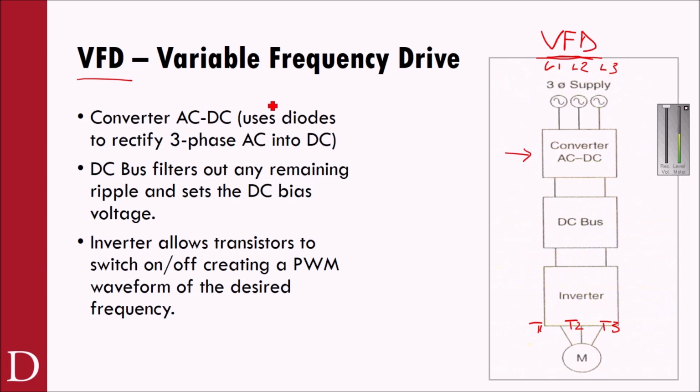Essentially in there's a bunch of diodes, and those diodes are used to rectify the AC voltage coming in into a DC voltage. You imagine diodes take AC that looks like this, and they basically rectify it into DC that looks like this. And then eventually they'll also filter it so that you end up with a nice smooth DC that looks something like this. But that's what's happening. We're taking the AC in, we're creating DC out of it.